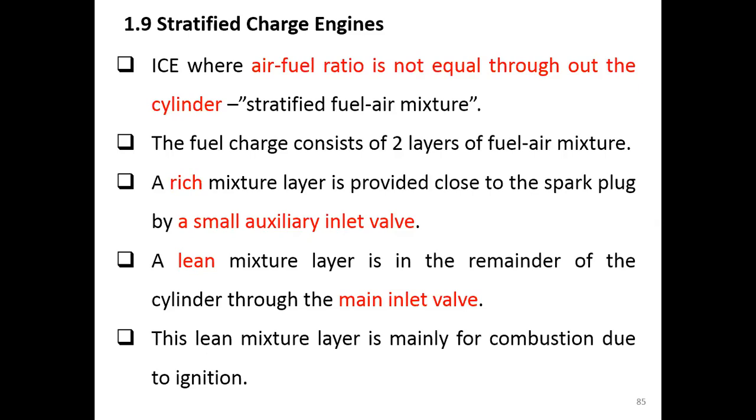So for the stratified charge mixture, we have a rich mixture layer, and this mixture is provided close to the spark plug by using a small auxiliary inlet valve. This inlet valve is used for providing the rich mixture, and it is positioned near the spark plug.